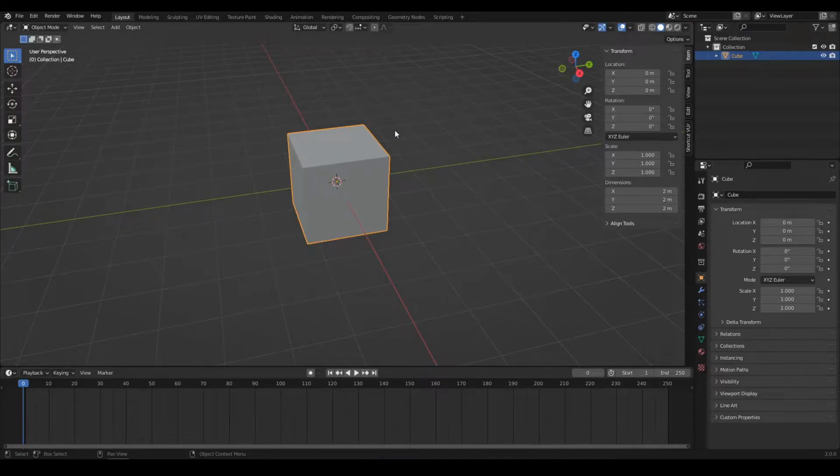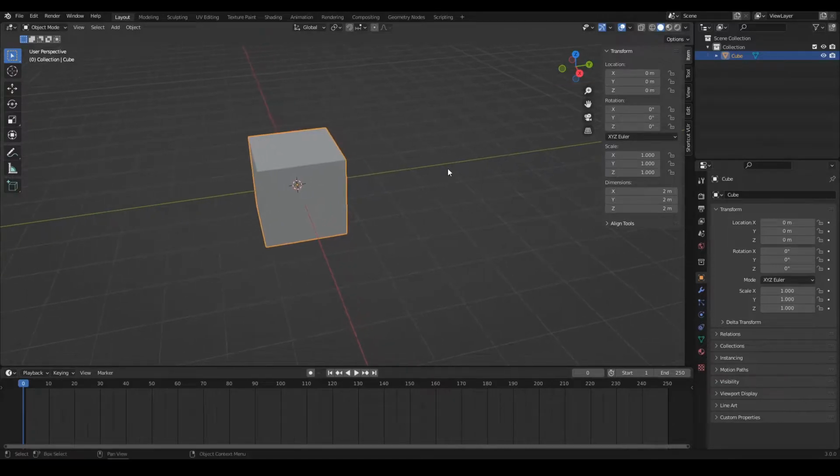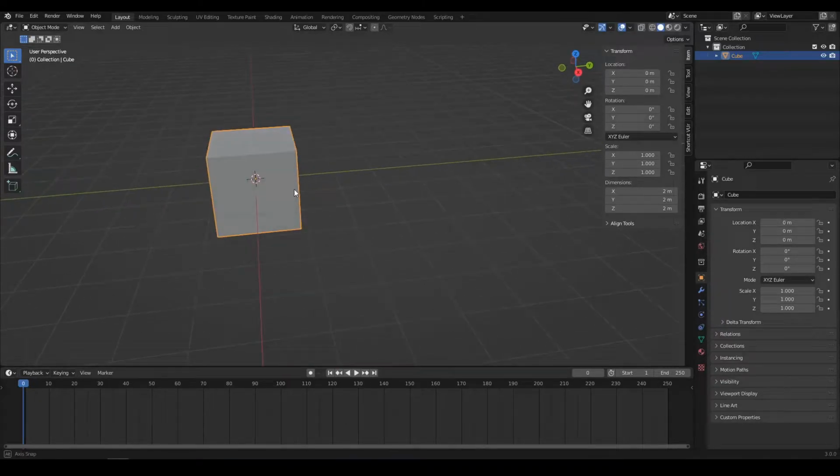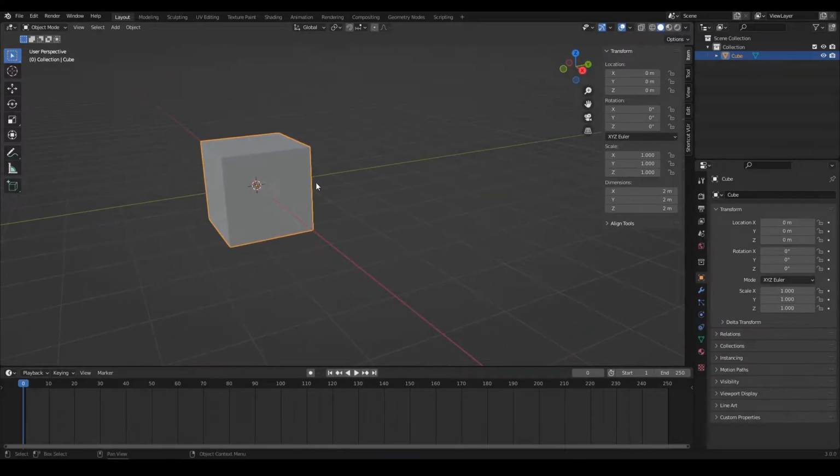And so to animate, now that we've got time, we need a parameter that will change its value. Let's keep it simple. We're gonna change the location y value on this cube over time. And for this, to just say to the software at this time the value is such a value, we need to add animation keys, or what is commonly called keyframes.